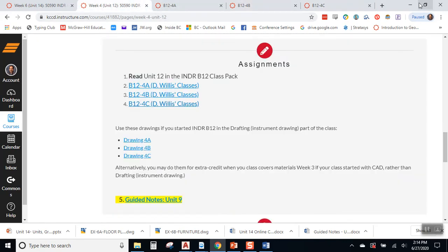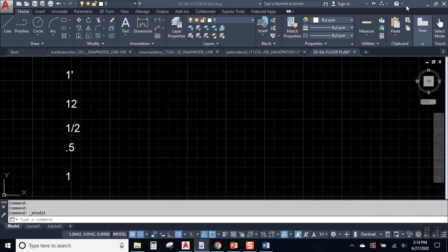So, I have to tell you, though, that AutoCAD is not measuring in inches. Yep, that's right. AutoCAD is completely unit neutral. So in the United States, when we type in 1 for the distance, we assume we're working with 1 inch. If we type in 0.5 or 1/2, well, the assumption is that's a 1/2 inch.